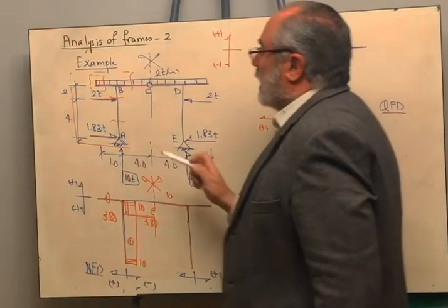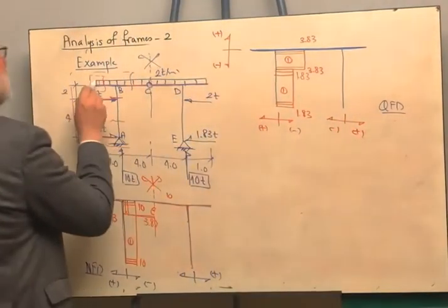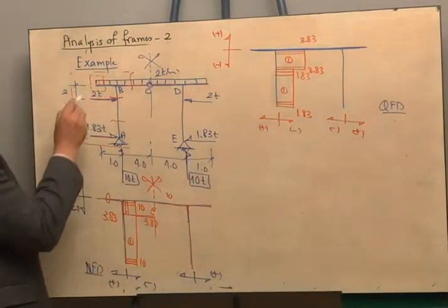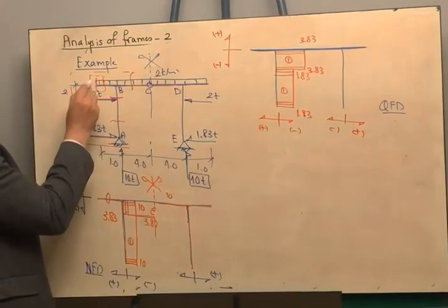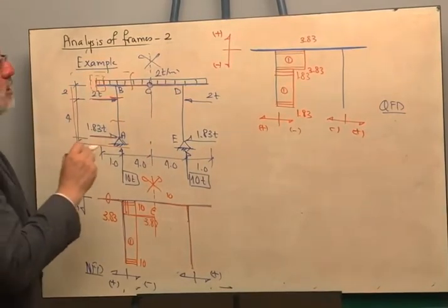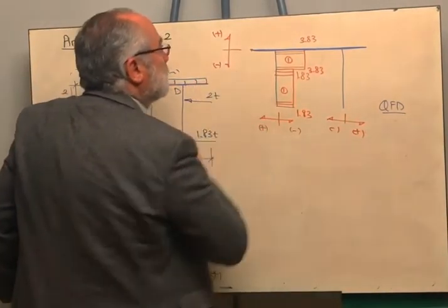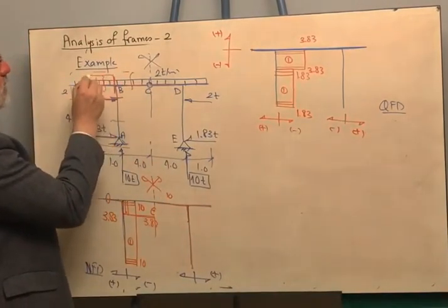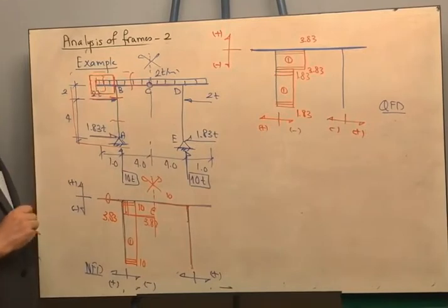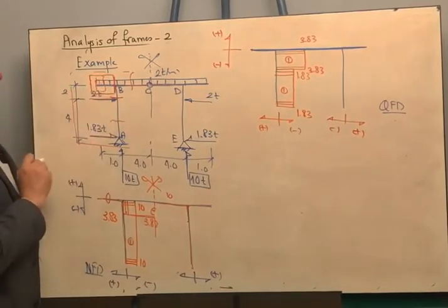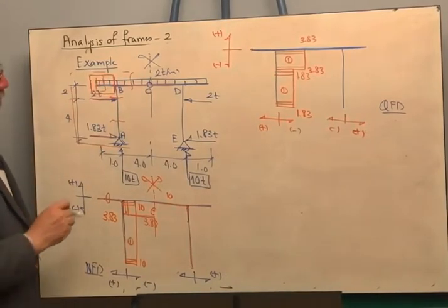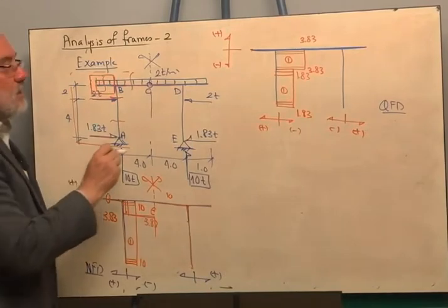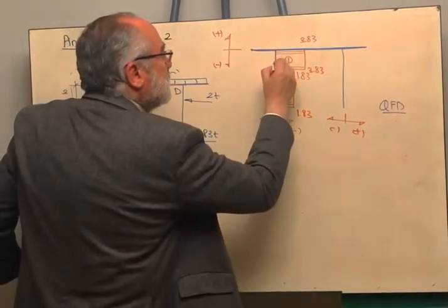Okay. Now let us take the beginning of the cantilever. Again, I am taking a section here. I am not taking any forces, so the shear at this point is equal to 0. Up till we reach this point, we take the left portion of the beam. It is 2 multiplied by 1, it is negative 2. So it is on my left-hand side and downward, then it is negative like that.